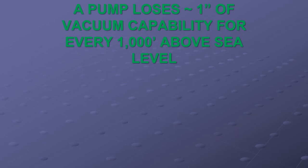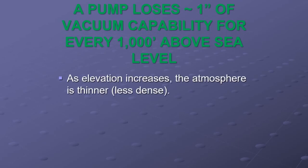So here we are. We've already covered this for the most part. I lose an inch of vacuum, or really I lose that 1 foot of draft capability, for every 1,000 feet above sea level. I also lose that 1 inch of vacuum capability in my pump for every 1,000 feet above sea level. It's the same thing.